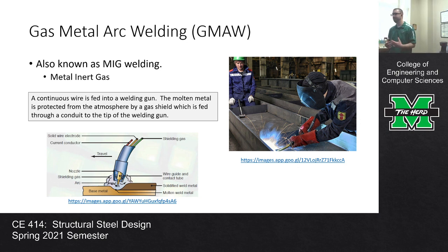And Trevor hit the nail on the head. Whenever you're dealing with welds, welds are, I don't want to say dangerous to deposit, but you do have to take certain safety precautions. For instance, if you look at the welder, he has the helmet on that's shielding his eyes from the ultraviolet, but he's also got gloves that go past his wrists. He's wearing long sleeve shirts because that light can kind of give you a sunburn.